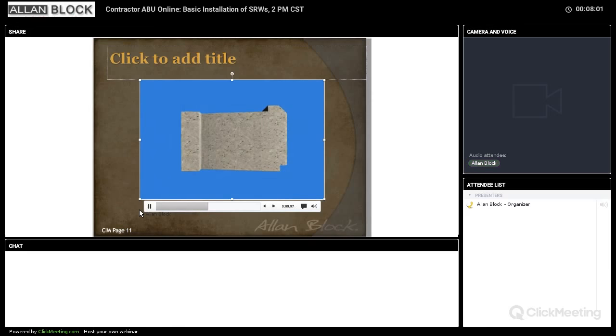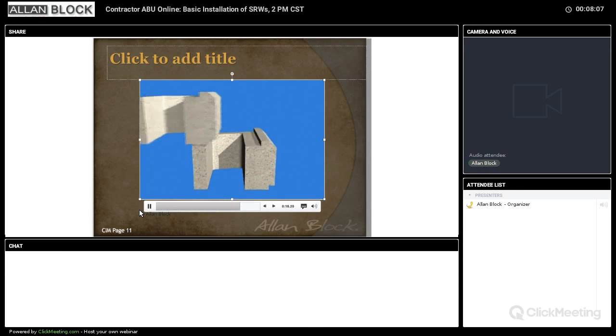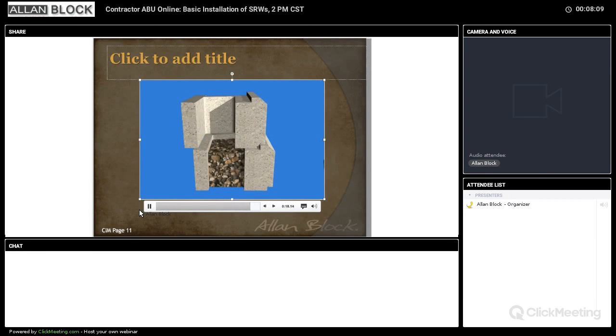It's got a raised front lip, a notch at the bottom. It's got wings on the side. The wings really are great for handholds. They allow you to pick up the block and move it around very easily. The hollow core allows you to put wall rock in the cores, which then transfers down between the courses, and when it's consolidated and compacted, it helps to add in the shear strength and the connection between courses.